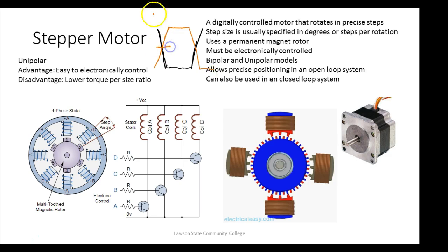The problem is your power is going to be maximum right here. So we get a power pulse right there, and a big power pulse right there, because we have current flow through the transistor while it's dropping the voltage during that switching time. But this power is averaged out. So you can use very small solid-state devices to control a pretty good deal of current.